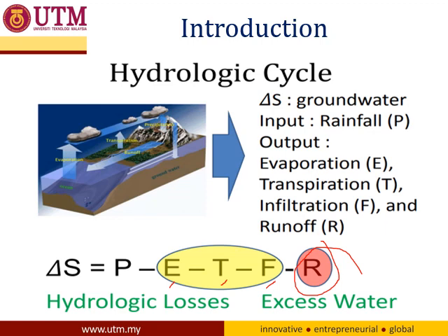For the hydrograph we have a base flow and the runoff. The base flow is there if there is no storm, and if there is some storm, then we will have some runoff water or excess water. So what we want to measure here is the whole hydrograph, the flow rate, the base flow, and also the flow during a storm event. It is usually continuous data.